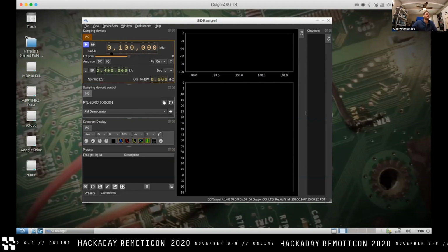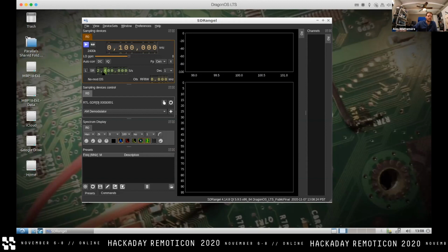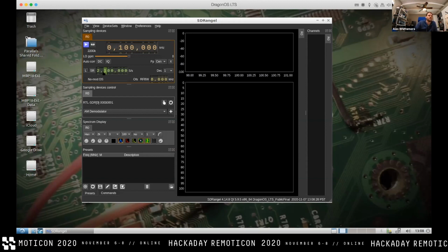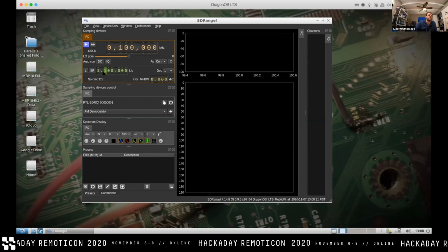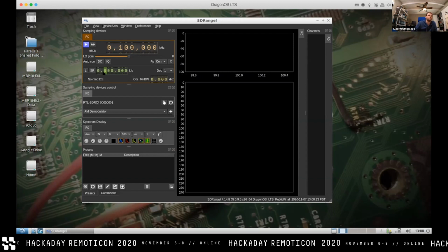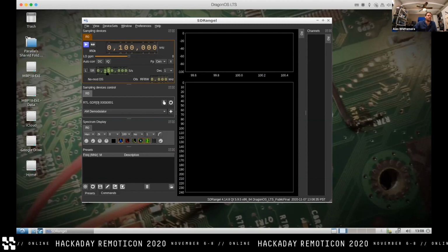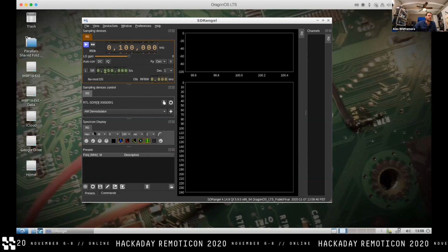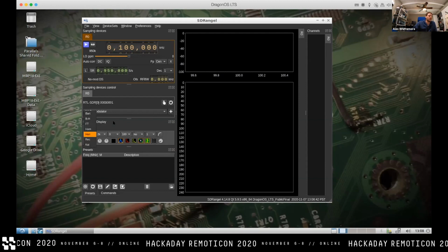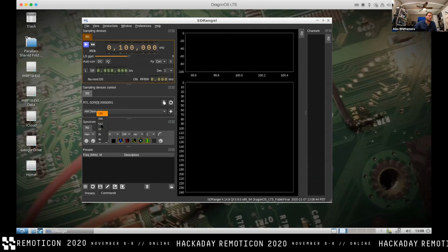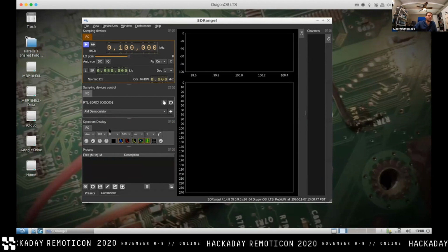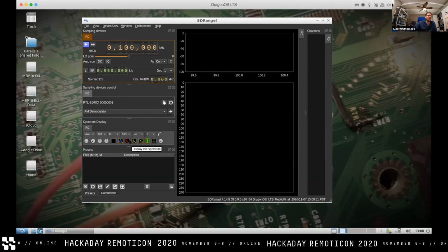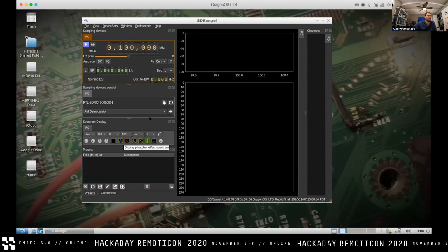But anyway, I am going to throttle that down for now because I fear that this virtual machine isn't going to keep up. I actually don't, but yours might not. So let's go down and knock that sample rate down to 950 kilosamples a second. And let's go down here in the spectrum display. You can leave the window as is. We're going to switch the FFT to 128 points. We'll show what these toggles do later, but leave them as is for now, and we can play with them.